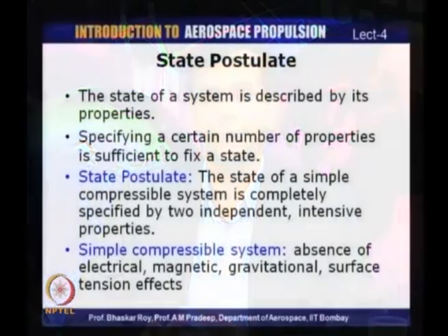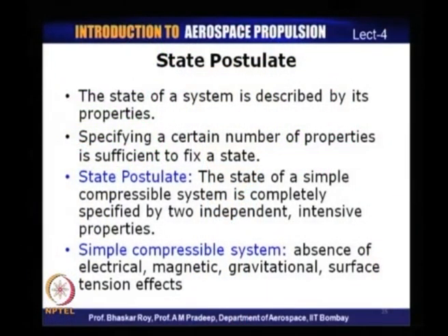Now, this is explained by what is known as the state postulate. The state postulate states that you can completely define the state of a simple compressible system by specifying 2 independent and intensive properties. Now, we have a new term here, simple compressible system.